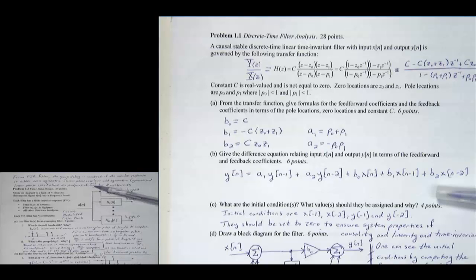All right, and we've talked about this quite a bit. You don't always have linear phase for an FIR filter. I saw several claims for that in your answers. An FIR filter doesn't always have linear phase. We'll see many cases in the second half where it's not true. It's true that the FIR filters we've seen so far in class have had the symmetry, either even symmetry about the midpoint or odd symmetry about the midpoint, but that's not always the case. But when it is the case, we have constant group delay.